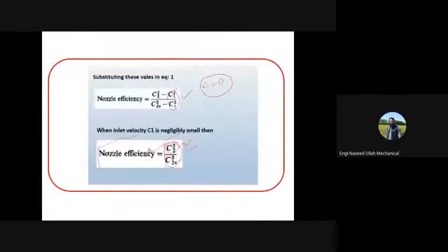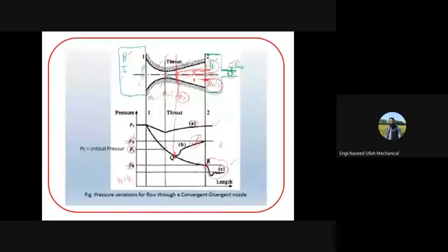अच्छा, इफ यू लुक बैक टू दिस थिंग, हाँ, ये मैं आपको बता रहा था। We want, let's say for example, this is your turbojet, okay, somehow down here, okay, upstream you are having your turbojet here, okay, and the exhaust is coming here. ये exhaust है. Now you want to accelerate this. You want to maximize this jet velocity. So you are giving this to, you know, this convergent divergent nozzle, okay, and at the exit, ये जो आपके पास होगा, this will be your Cj.